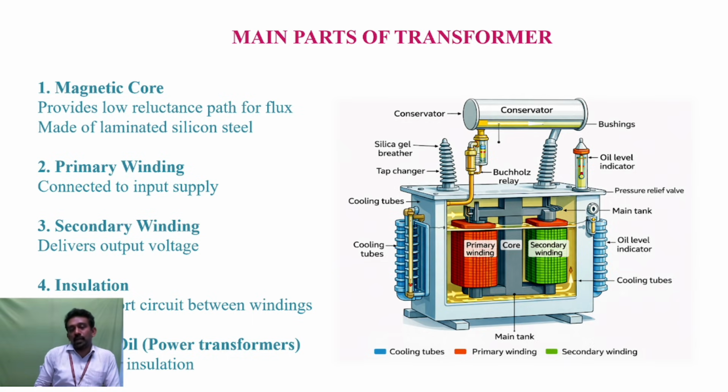It is basically made of laminated steel, in which multiple stacks are used to form this core. These multiple stacks are used to reduce the hysteresis loss and eddy current loss, due to unwanted current circulation induced by the magnetic flux by means of electromagnetic induction. So it is made up of laminated silicon steel, and this gives a good efficient performance of the transformers.